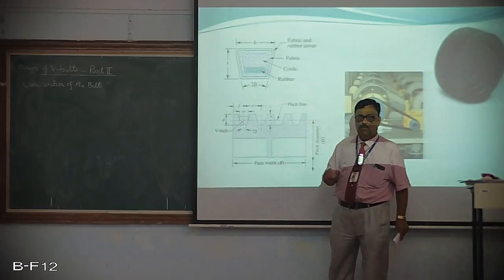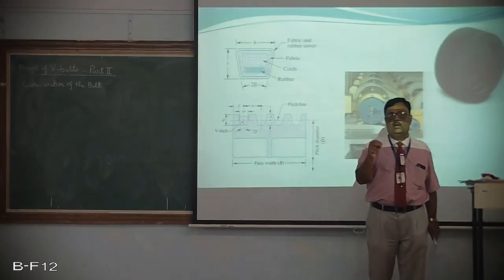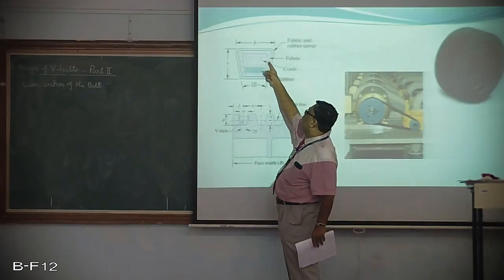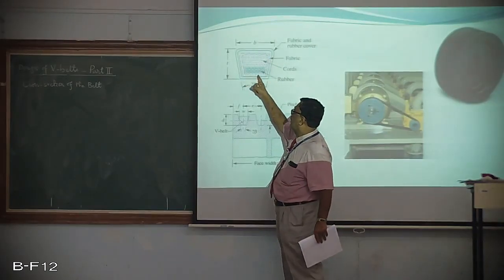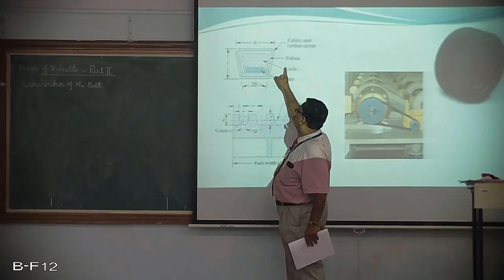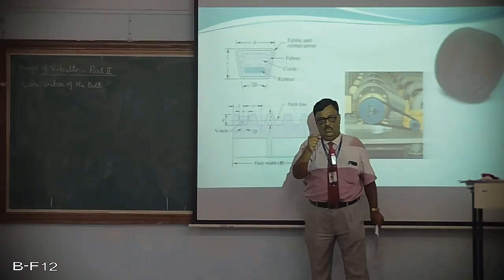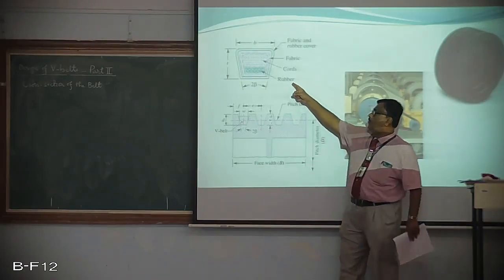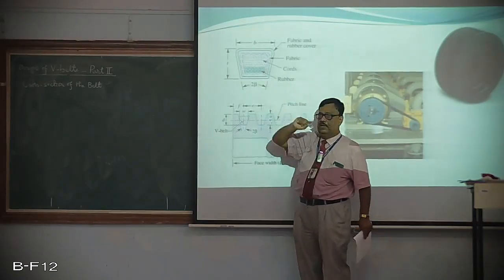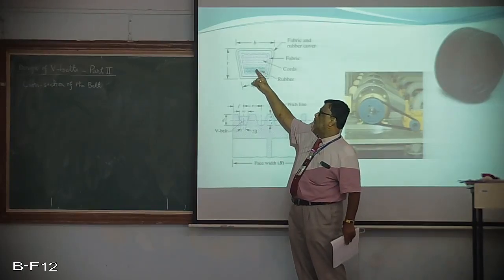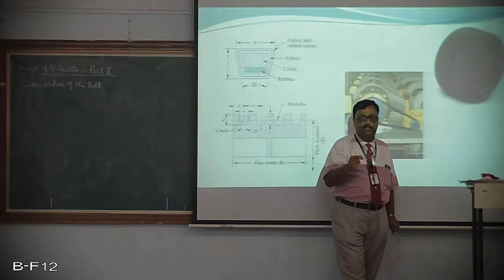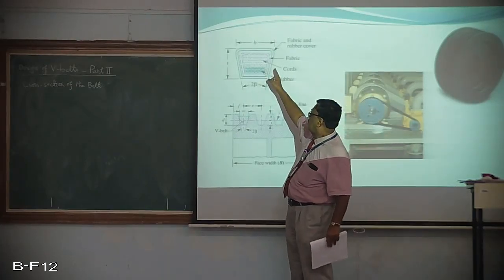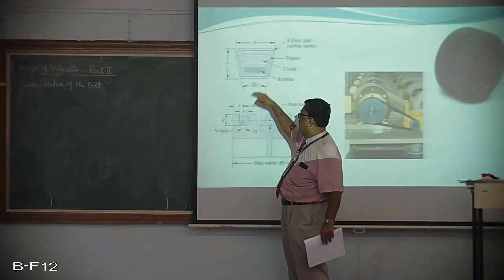Inside, these belts are molded. You will find a composite section with a fabric lining next to the outer layer, and inside that there are steel cords along the length of the belt. After that there are rubber linings, provided at the bottom to give the belt flexibility. So the construction of the belt is wedge shaped.